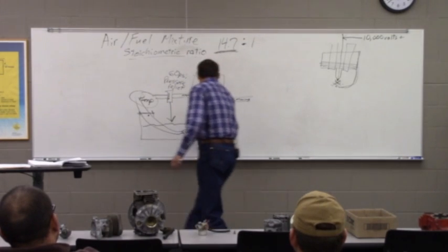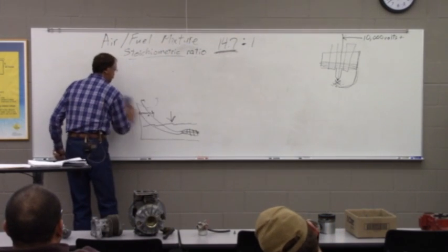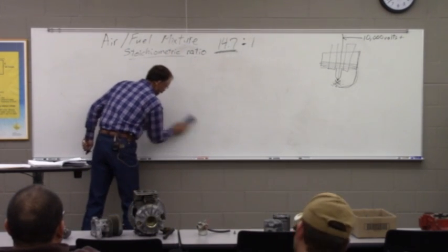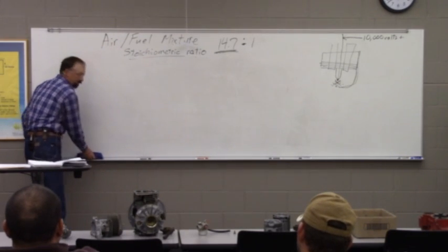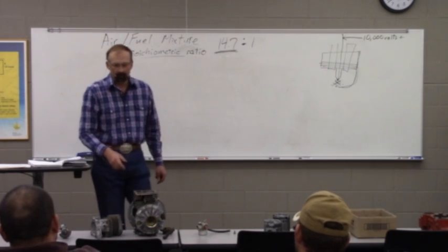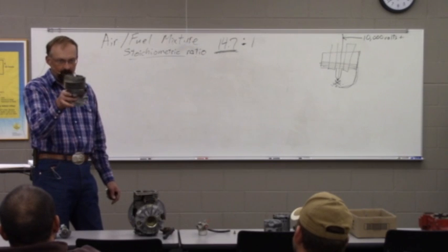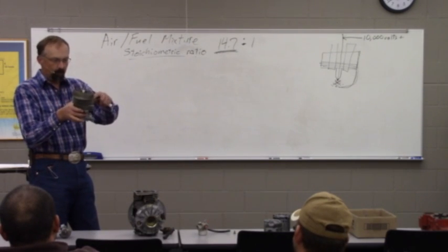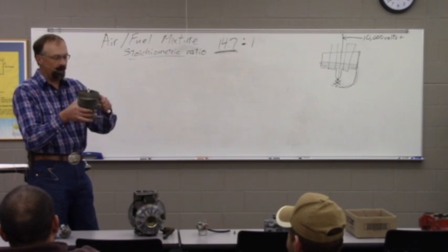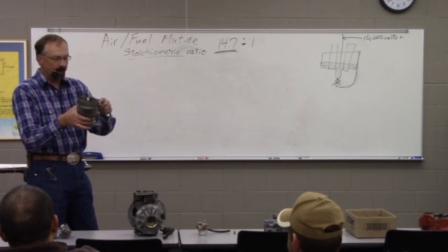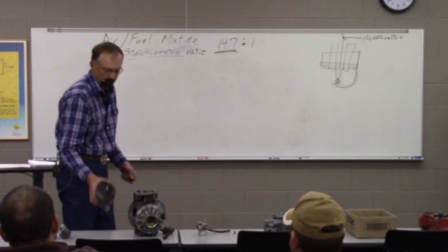So the last thing on the agenda for tonight was cooling system, and I'm going to be specifically talking about water cooling, although we'd already talked a little bit about air cooling. These two engines are air cooled, and of course they've got those fins on them, so there's more surface area here, because as the metal heats up, we're wanting to transfer that heat from the metal to the air, and the more surface we have to work with there, the better that heat will transfer.